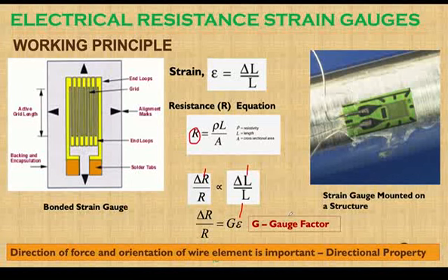property and the arrangement. That means when this strain element is subjected to a strain in this direction, then the element will elongate in this direction. All these elements will elongate in this direction, thereby a change in length happens for the entire length of this element. So that change in length will reflect in a change in resistance. If this resistance element is part of an electrical circuit, typically it will be part of a Wheatstone bridge, where there will be 4 resistances in a bridge, and all the 4 resistances will be of the same resistance and same property.